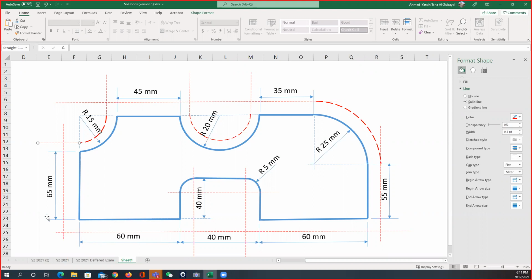Technically, we're looking now at the top of the work part. Now let's consider that my phone is the work part. I'm looking at the top surface. Looking at the top surface, this will be the x-axis. The lower level, the horizontal one, is the x-axis. This will be the y-axis. Upward is the positive. And the depth from this surface below, this will be the z-axis. Above that is the positive z-axis. Below that is going to be the negative z-axis. I'm not going to work in detail with the z now. I'm only going to use it for a while, but it's going to be there.